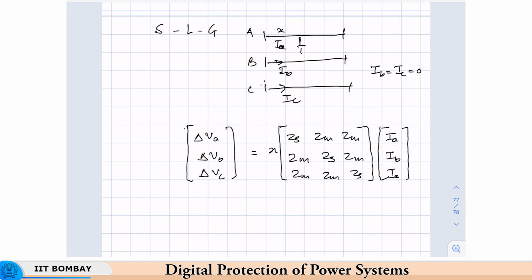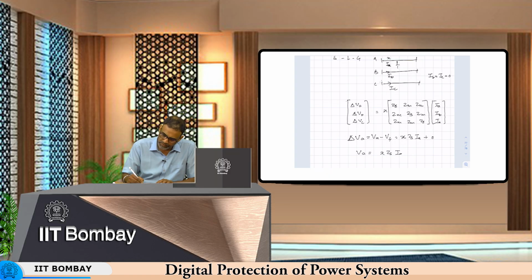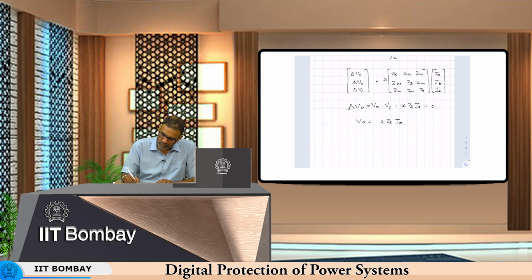Now if we do VA by IA, simply do VA by IA as we did in the earlier cases, we will get X ZS, which is not what we want. Remember, we want to get X of Z1. So what do we do? We will now manipulate this equation here such that we get X of Z1 on the right hand side. Okay, we'll start with this equation here. VA is equal to X into, we will subtract and add ZL.